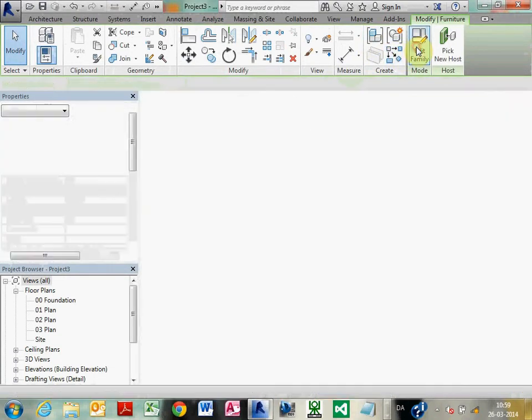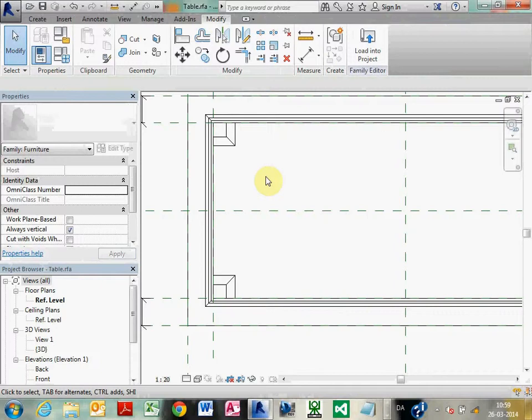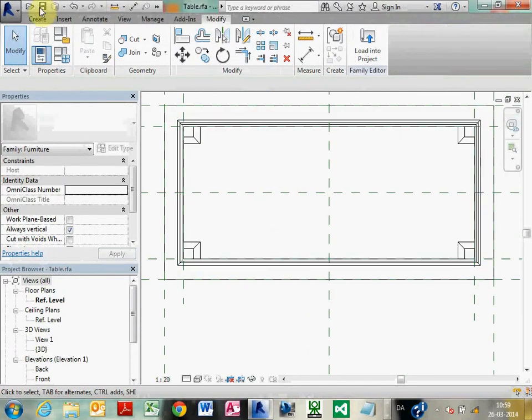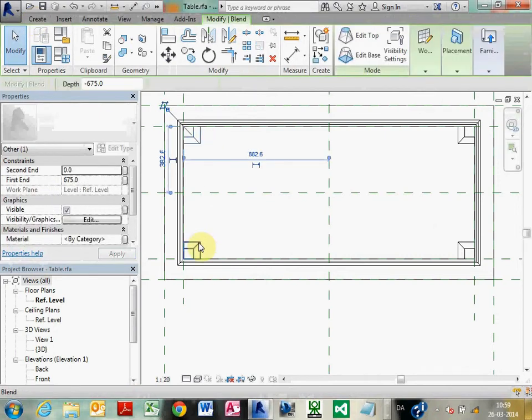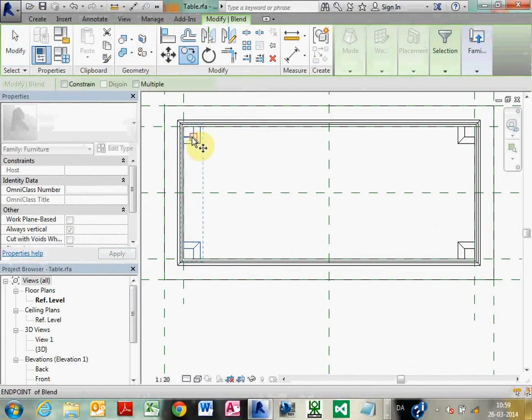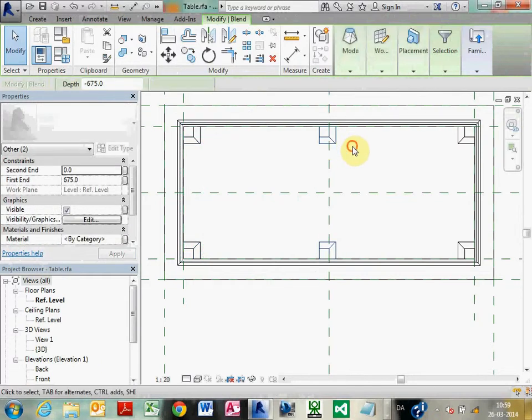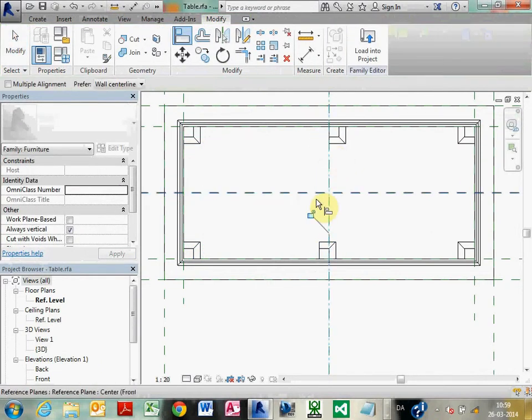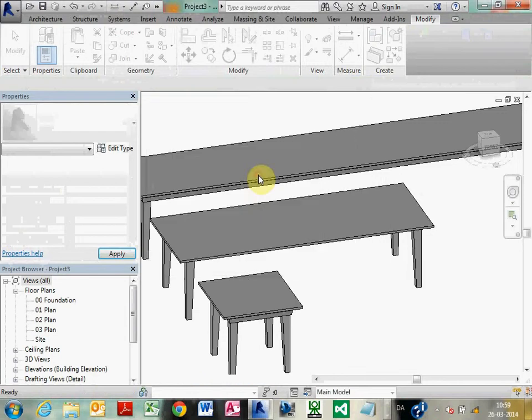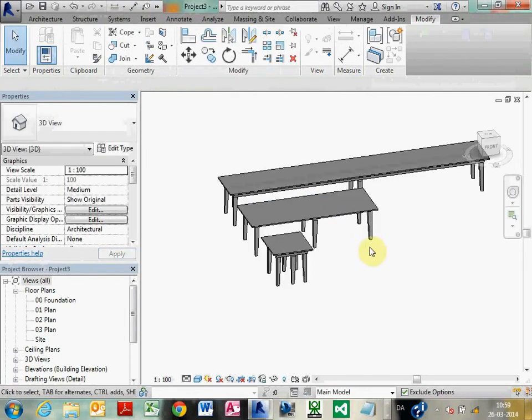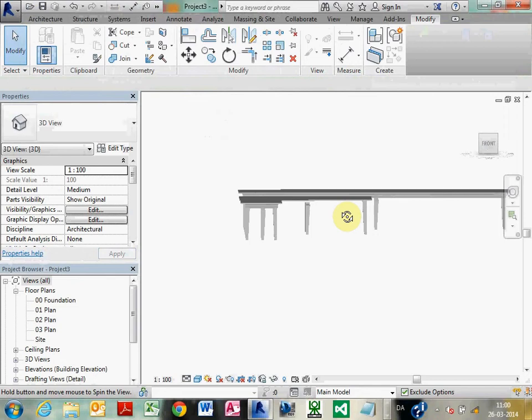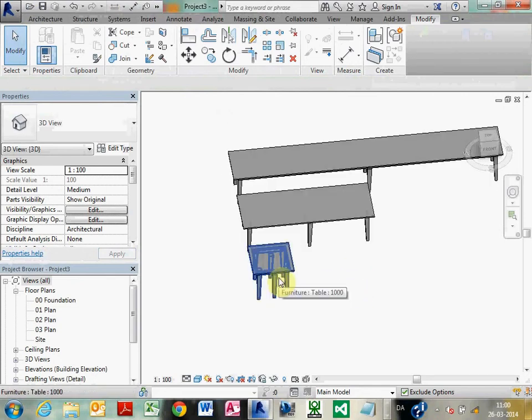Again, I go back into the family, because I could see when the table gets long, maybe they need some extra legs in the middle. We just make a copy. Maybe align them to the middle, approximately. Like this. Beautiful. But first thing, I need to control the height, and then this maybe should be on the long tables only.